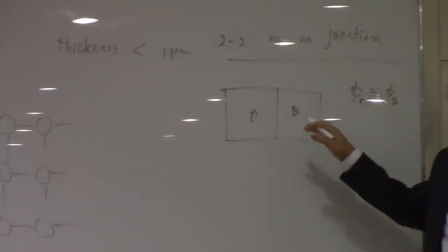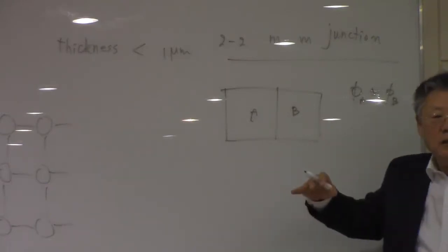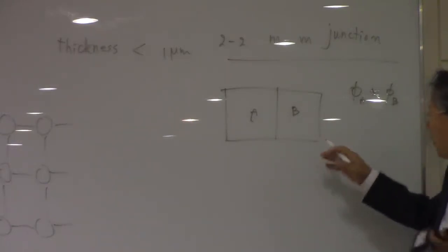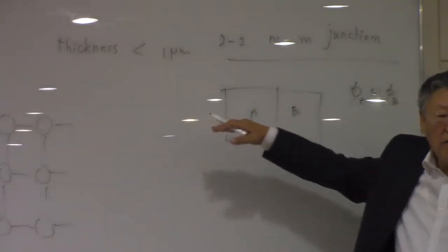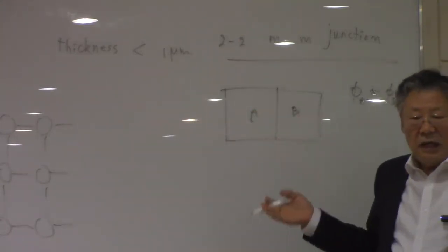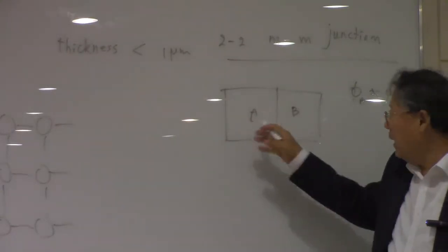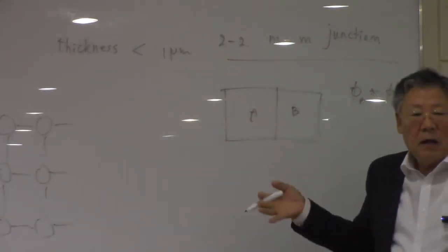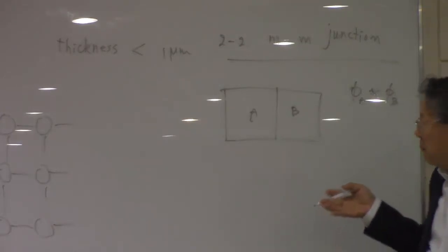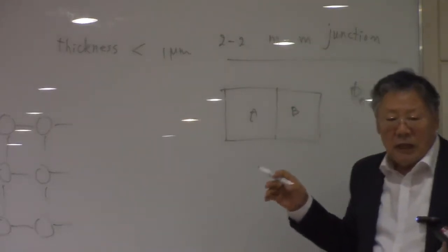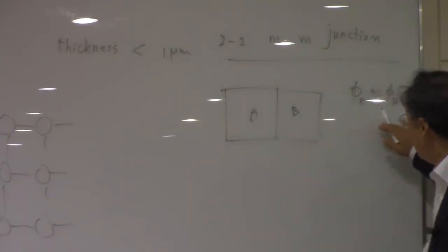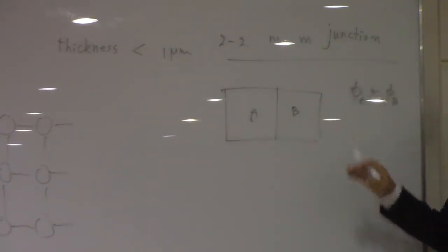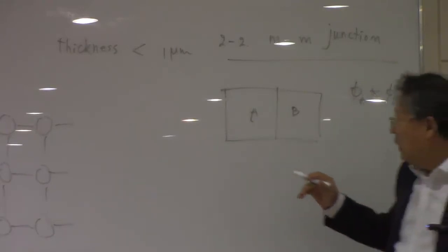In other words, they have different Fermi energy levels. But if you make a junction like this, the Fermi energy should be equal everywhere, so that there is a net electron flow between A and B to set up some field. But physically speaking, in metals there are so many free electrons that this internal field is not that serious.